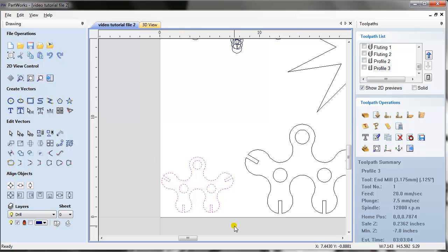So what I'm going to do here is select all of them and hit Control C, just copy. I'm not going to move it anywhere, just going to paste right there, Control V. By doing that, it pastes the shadow vector exactly at the same place, but now using the arrow keys on the keyboard, left, right, up and down, I can actually move the vectors. As you can see on the screen, it's moving, and I can rearrange them the way I want.